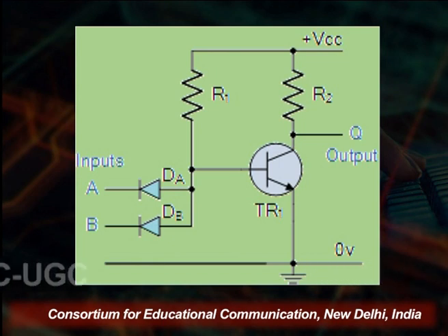Similarly, we can do this by using a transistor. Two inputs go through the diodes, then into the transistor. After the transistor we take one ground and one output. The resistance can be varied. So the simple two input diode resistor AND gate can be converted into the NAND gate by the addition of a single transistor, that is the inverter NOT, using discrete components such as a diode, resistor and transistor to make the digital logic gates.